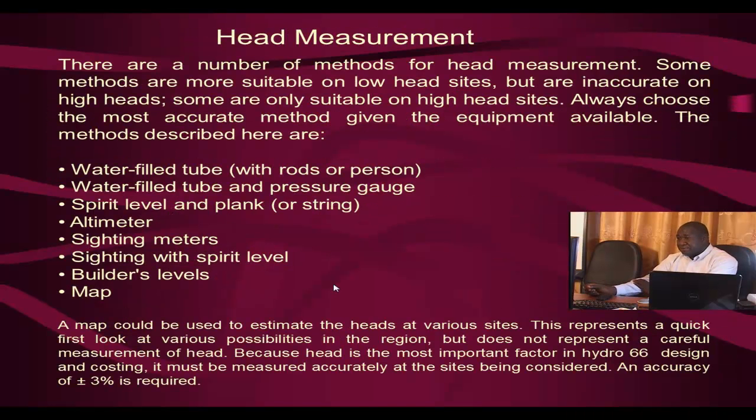Head measurements. There are a number of methods for head measurements. This includes water-filled tubes and pressure gauges, spirit levels, altimeters, sighting meters with spirit levels, builders' levels, and the use of maps.